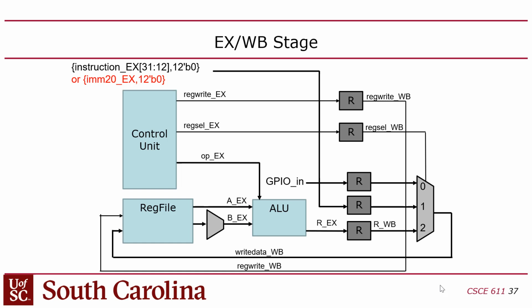Yes? You kind of simplified the reg file to the ALU on this particular graph. Is there actually the mux right there? This one? Yeah, I haven't gotten to that one yet. So that's a second mux. This one controls what goes into the second input, the B input on the ALU. And what are the choices you have for that?